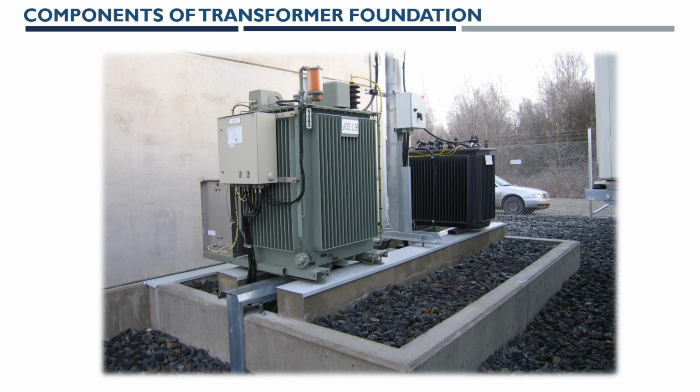So this is another transformer foundation showing the metal filling inside the transformer bund for the oil spillage. So this is also having hauling beams here and the transformer bund wall around the transformers. Also some equipment support, and the control cable support is also fixed to this transformer main block.